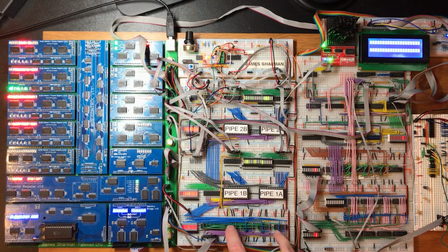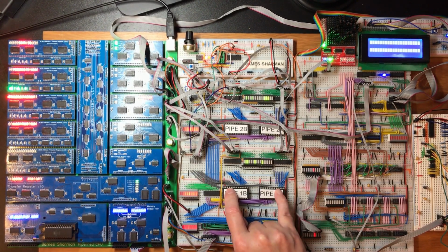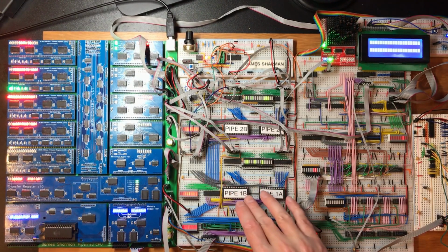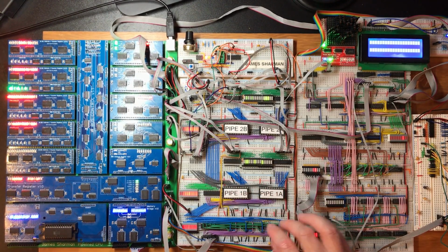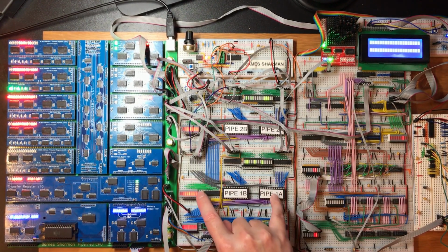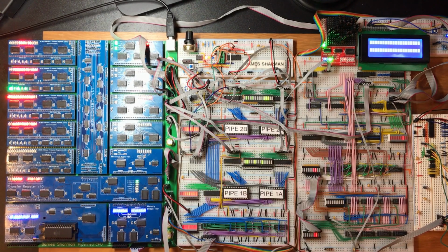And so we added the functionality to both detect that and handle it by redispatching the immediate load that's been held in the latch chip here. Now the one thing we didn't do is add anything to pipeline stage 1 to prevent that instruction. And so I would like to add that functionality, but I'm going to do it straight into the PCB design. That may be asking for trouble, but there's just no room here to try and do it without a radical rework of the existing breadboards. And this is getting pretty packed as it is.